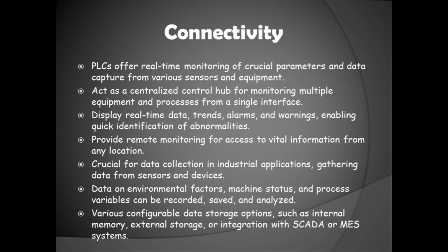PLCs offer a variety of connection choices, including Ethernet, Modbus, Profibus, Profinet, DeviceNet, and many others. These protocols provide dependable and quick data interchange, status monitoring, and control command transmission between the PLC and connected devices.